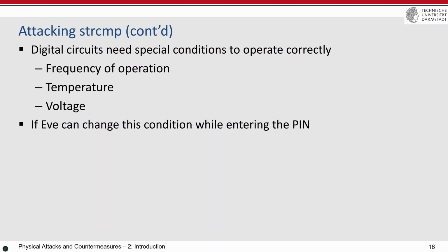The problem of this kind of attack is that every time you want to get access or skip that instruction, you have to inject the fault. Either you know exactly at which clock cycle you need to inject the fault, or you try a lot of different cases. For example, you inject in the first clock cycle, it doesn't work. Injecting in the second clock cycle, it doesn't work. Till once it works, and once it works and you get access to the secure data, then that's all.